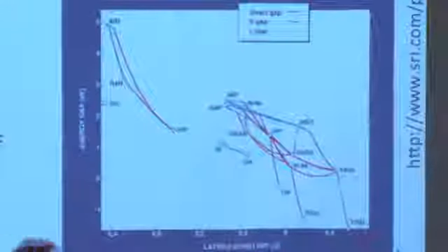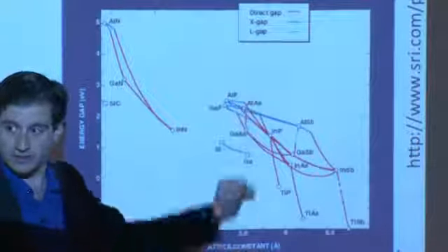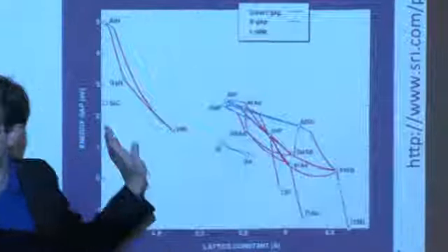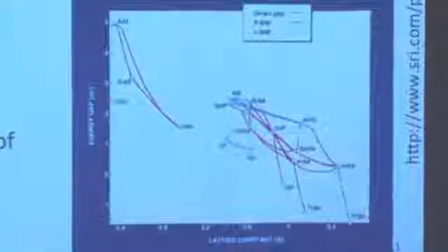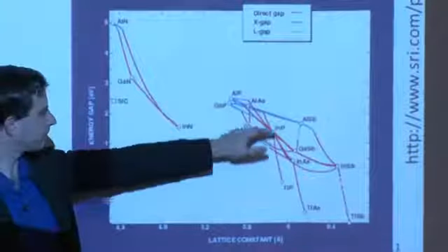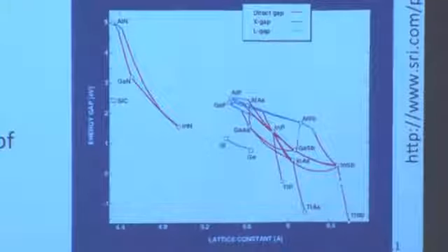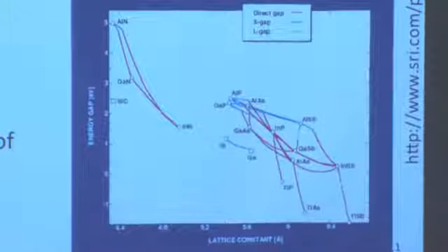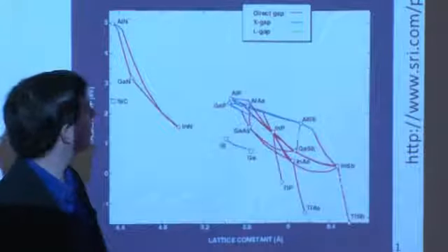And so you need to make sure that the materials that you grow are matched in lattice constant, but varying in band gap if you're trying to grow a multi-junction device, if you're trying to grow a very high efficiency solar cell device. And so the growth or matching of materials one on top of another is important, especially for the multi-junctions, also for some of the single junction materials, if you really want to minimize the interface recombination.